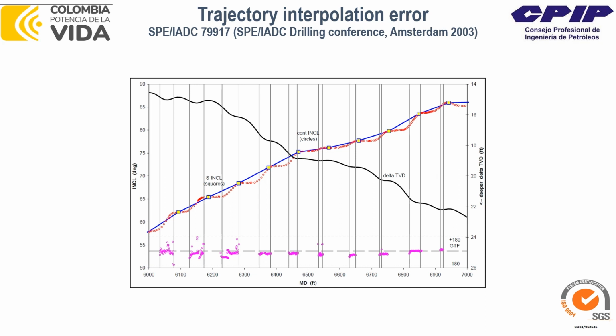It's not a difference between plan and fact. It's a difference between the actual well, which you see on the papers, and the actual well, which is located in the earth, right? Without this analysis, you would never see the differences exist. So by drilling these 300 meters, he already gets almost 2.5 meters of error in TVD.